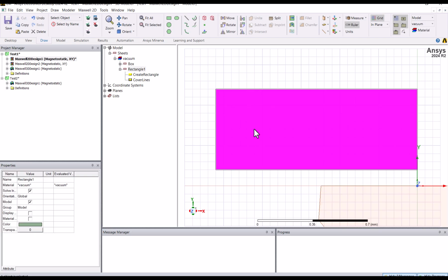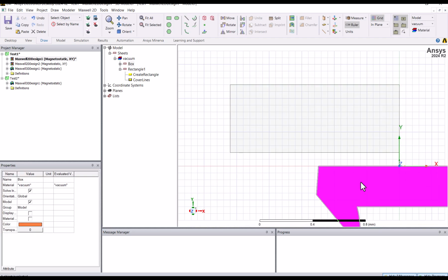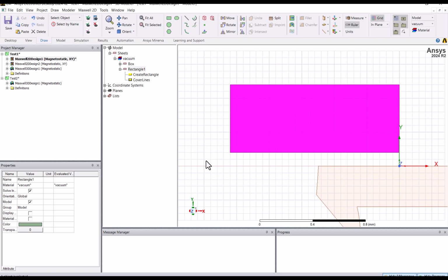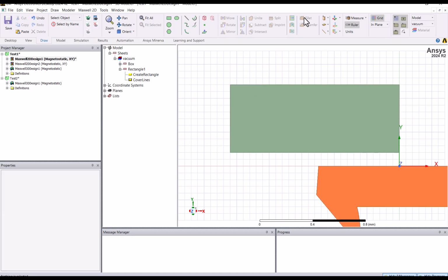Currently you can see the selection mode is object, so whatever you select, it will select the complete object. We know that we will have edges, faces, and even points or vertices. In order to apply fillet and chamfer, we need to have vertices or points selected.